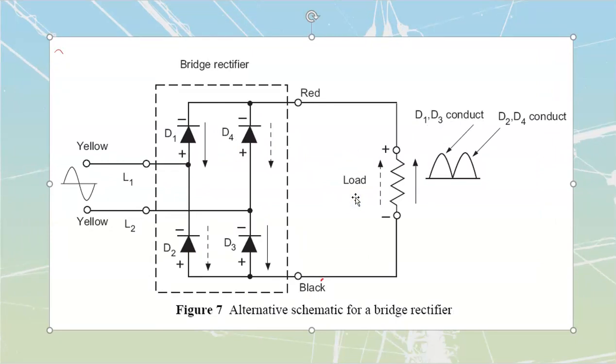You need to be very careful with these types of drawings that you do not connect, if you're making drawings, that you don't place the AC in on the DC side, because if you place the AC in, you're going to end up with a dead short off of these things. Note how all these diodes are going in the same direction, and that I'm coming into the center of the diodes over here, and then I'm passing out to these.